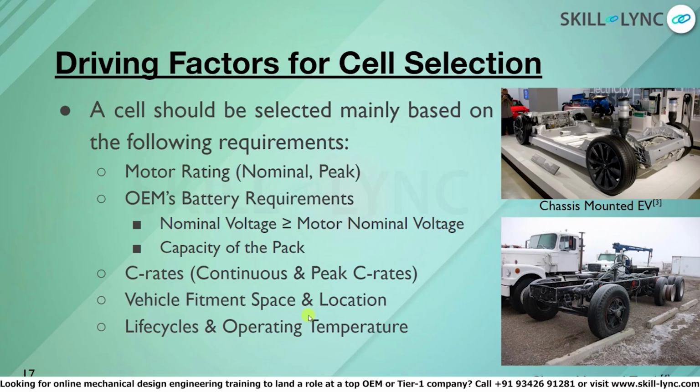Basically, chargers currently in India are continuous C rate. So you connect the charger to the vehicle, it will be charged at a continuous rate. It's a standard rate. Whereas when you say discharge, it's always dynamic. You cannot expect a single rate at which the discharge would happen, because it's a road. You will accelerate, you will decelerate, you will brake the vehicle, etc. So that is how your C rates are important. So that plays a vital role in selection of the right cell.